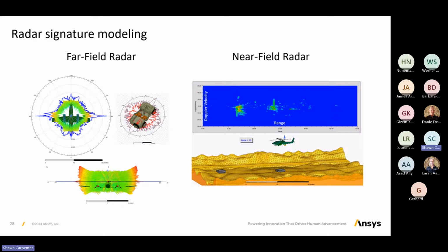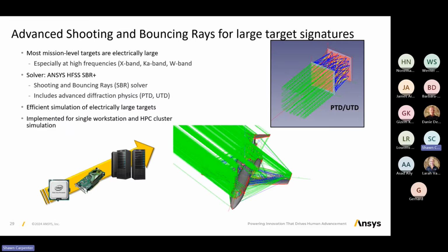If you have a reasonable CAD model for that target, we can provide you with an analytic model for RCS for copole and cross pole scattering. And I'll show you an example in a few minutes. But for motion-driven scenes, we can also perform near-field radar simulations, which might be also of interest from a variety of industrial applications as well as aerospace and defense applications.